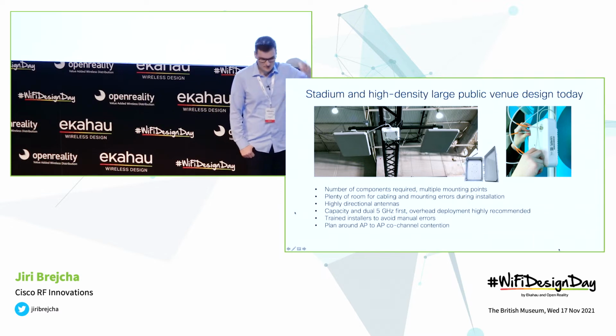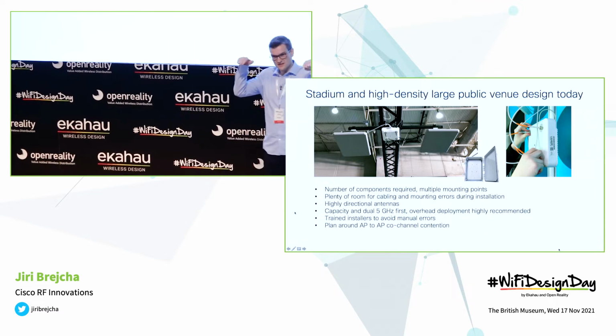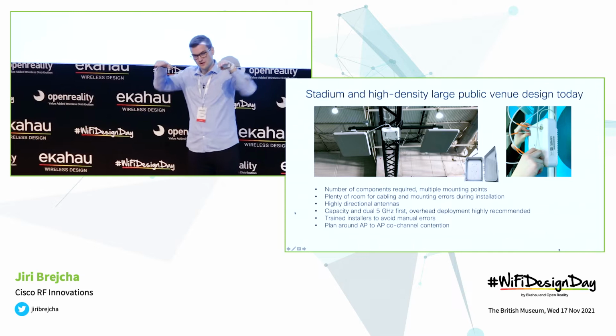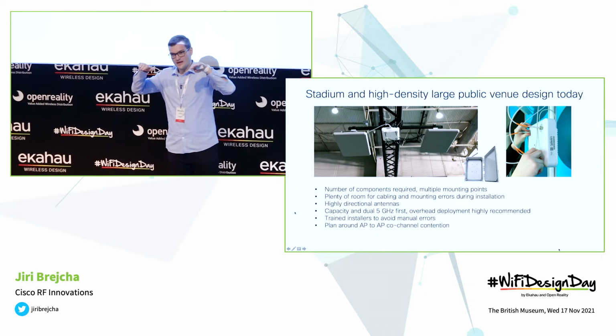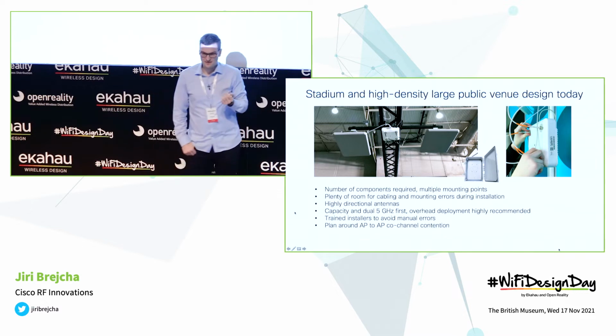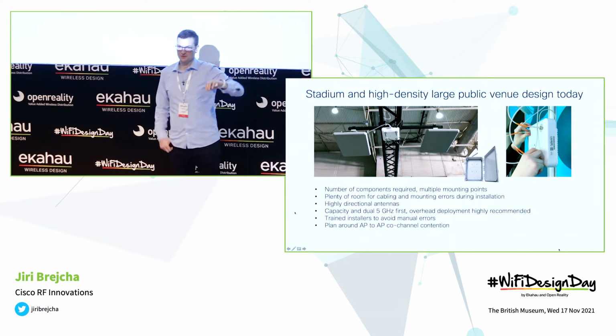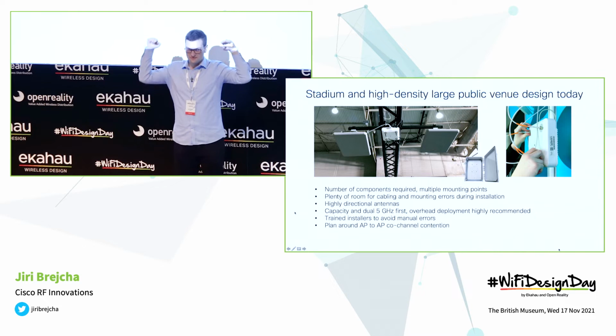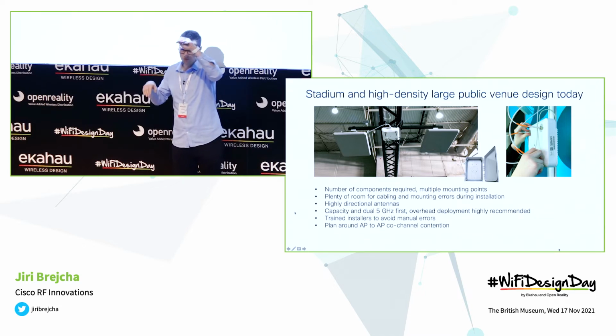and that gives you really good capacity over the air. The benefit of this is that you can have 2 different antennas, you can have same antennas. Obviously you can aim them, you can change the down tilt on that. The challenge though has been that you're deploying an AP, you're deploying 2 antennas. So you have 2 antennas to mount, you have an AP to mount, that's 3 mounting points.